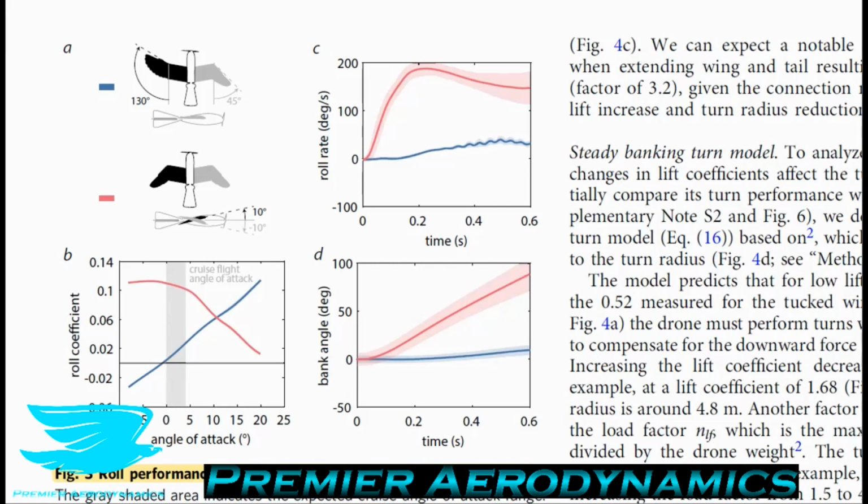if you are now pitching the wings up and down at, let's say, 20 degrees or even 15-degree angles of attack, increasing the angle of attack by 10 degrees is really asking too much of most airfoils. They're going to stall. The other airfoil, you can drop that angle of attack by 10 degrees and you're going to be fine, still well in the attached boundary layer region. But the other wing, which is stalling, you're going to be reducing lift on there anyway. So the amount of roll that you can produce from this maneuver at high angle of attack is not very much compared to at low angle of attack.